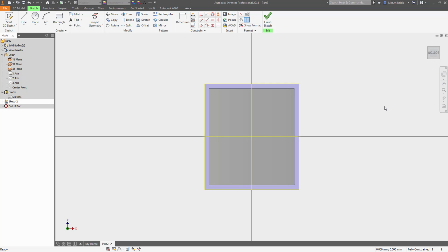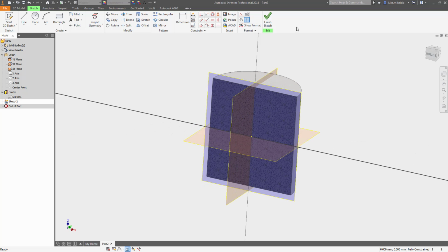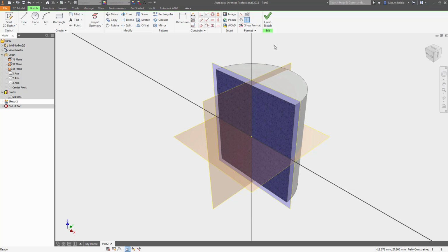I didn't know about this for the longest time, and I think someone on social media pointed it out, and it totally changed the way, because I used to always shut it off temporarily, so this happens automatically now. Great feature. Again, right click on the home key, perspective with ortho faces. I'm going to hit F7 now. What F7 does is that slices my graphics wherever my sketch is. Remember, I put that sketch on this plane, so this is right where I'm working.